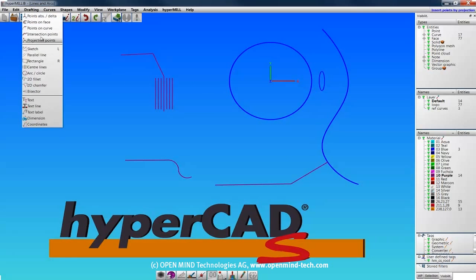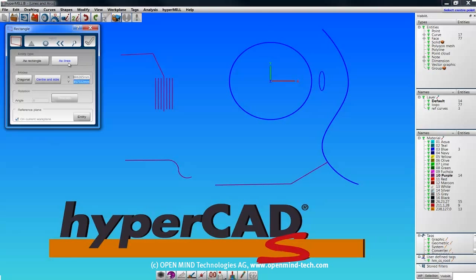The rectangle command creates a rectangle either as lines or as the rectangle entity type, which is a closed contour with a center snap point. For modes, we have diagonal, where you choose two corners, and center and size, where you choose the center, and then the size can be dynamically dragged or typed. The rotation angle can be dragged or typed, or can be aligned to the direction of an existing entity. The reference plane can be the current work plane or specified by a planar entity.